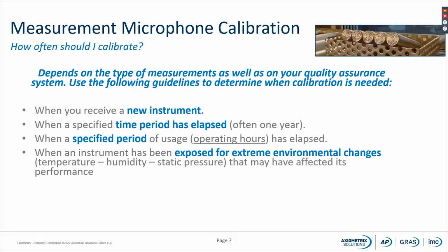When an instrument has been exposed to extreme environmental changes, such as changes in temperature, humidity, or static pressure, that might have affected its performance, it's also a good idea to perform a new calibration.